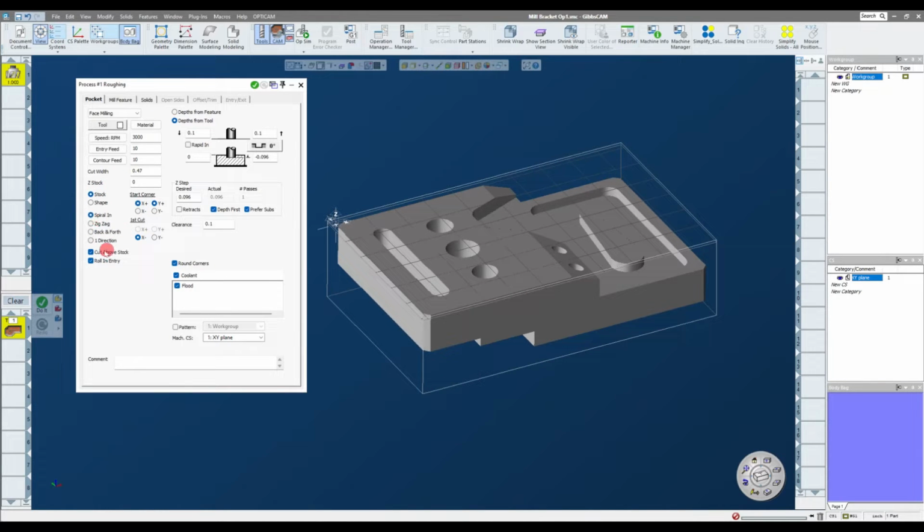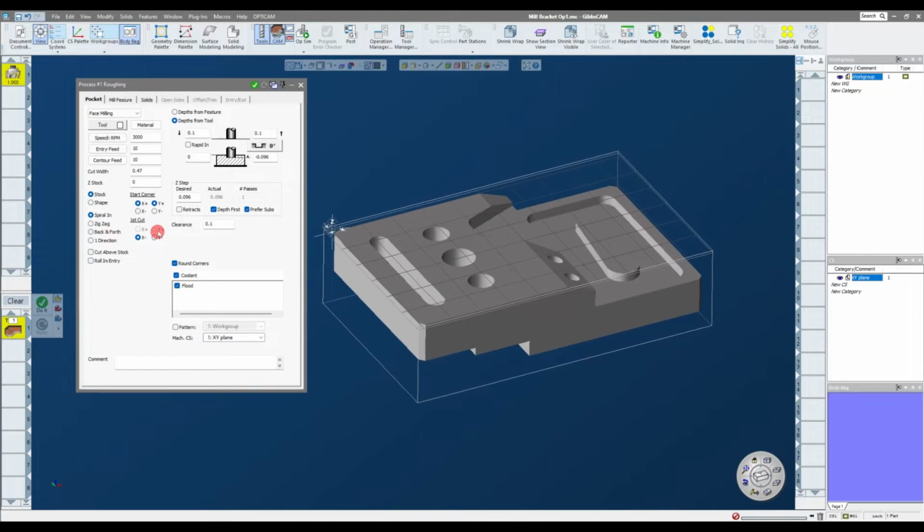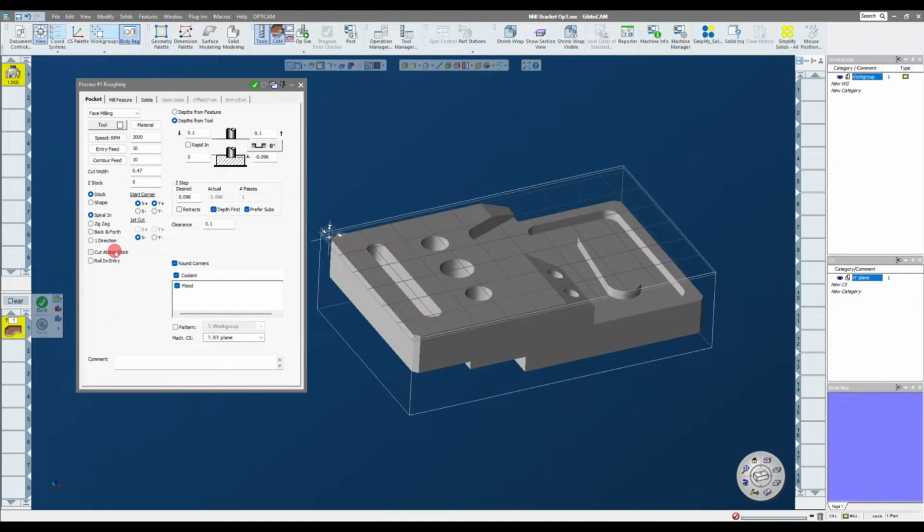You have a couple of different options down here. You have start, corner, finish, cut. If you're not necessarily sure exactly how you want to process this cut, this is one of the great things that I like about GibbsCAM. It's a very visual software because we use tiles. We don't use a lot of text menus for selecting options. So I like to tell it that as soon as you have a green checkbox, you're ready to generate a toolpath or attempt to generate a toolpath. I like to give it the minimum amount of information possible, see some toolpath on the screen, and then quickly make whatever changes I deem necessary from that toolpath. You don't have to populate 20 or 30 different options exactly right to get toolpath. It's very easy to start generating toolpath.